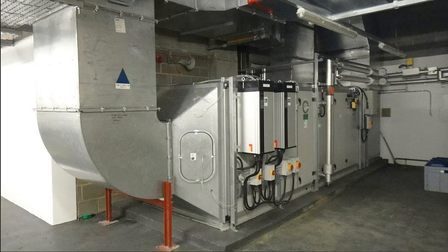The second AHU which we're going to look at is slightly different. It's only got a cooling coil on it. So the air is coming in here and it's being sent off again, off into the space. But you'll notice that this one has got some VFDs on it, some VSDs, variable speed drives or variable frequency drive, and they control the speed of the induction motor, which is connected to the fan.